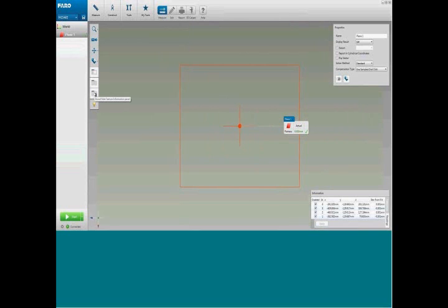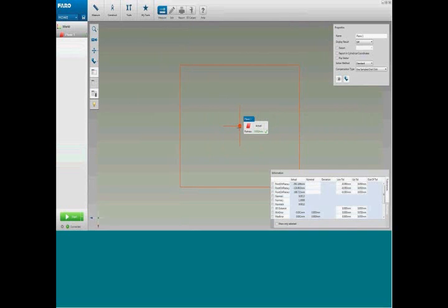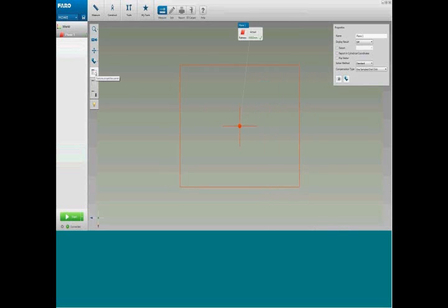We then have the feature information panel, which when open, will show the results of the measurement. So we have the actual. We have a nominal, where again we can enter drawing values. And we have a tolerance column, which allows us to change the tolerances to suit the drawing. To the right of this box, we have small tick boxes, which when selected will add that feature to the report, but also to the label, as you can see here. To hide any of the panels, we simply click the tab again.